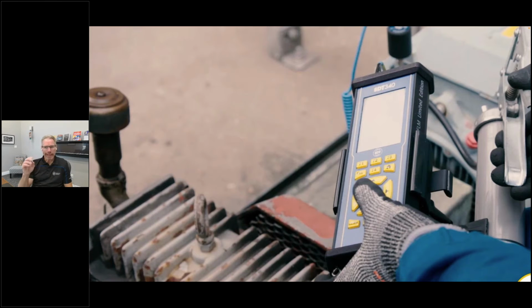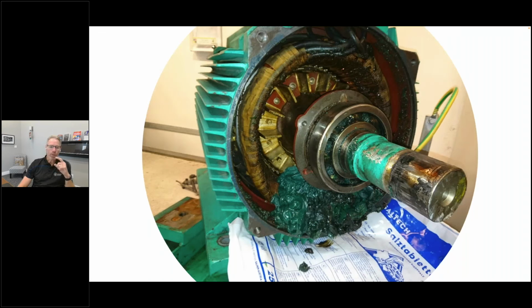4,000 years and counting, and industry still seeks a workable method to determine when and how much lubricant is required to maintain that perfect separation of surfaces. Well, we can use statistics to frame or suit our inquiry. We can even use statistics to manipulate our inquiry. For rolling element bearings, it's a well-established fact, it's a statistic, that poor lubrication practices are the leading cause of premature bearing failure, that 40 to 80% of reliability issues are rooted in poor lubrication practices.